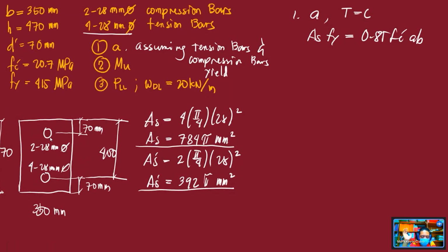it doesn't necessarily mean that the design of the section is doubly reinforced. It could be that the reinforcement on top is just there so the stirrups have something to attach to. Can you connect stirrups? This is the main reinforcing bar, with bars on top and at the bottom.